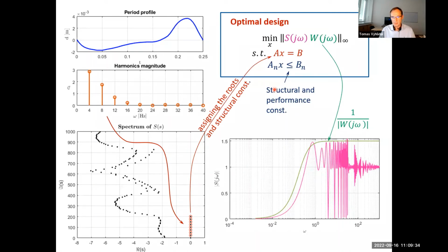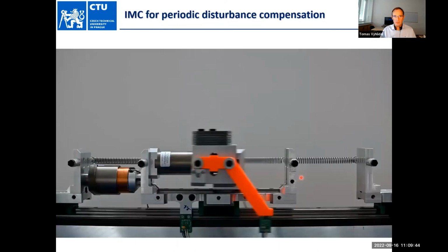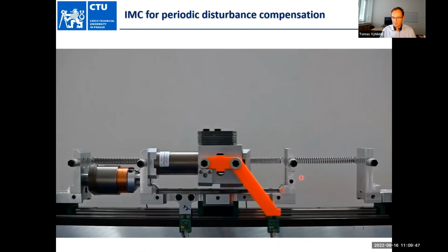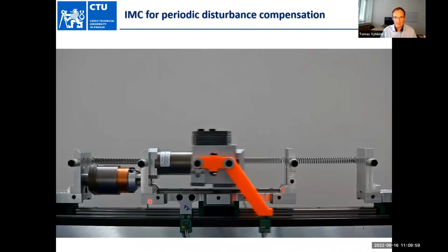And the synthesis is done by a robust frequency domain synthesis, H infinity, by minimizing the weighted H infinity norm. So these are results which show that it works. Really, even though we have this quite nasty periodic signal, it works surprisingly well.